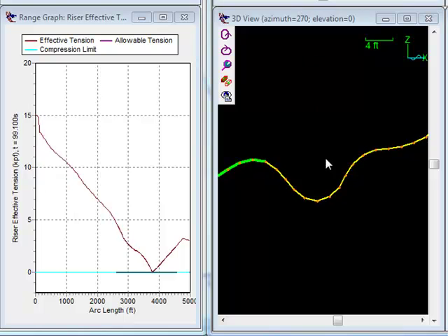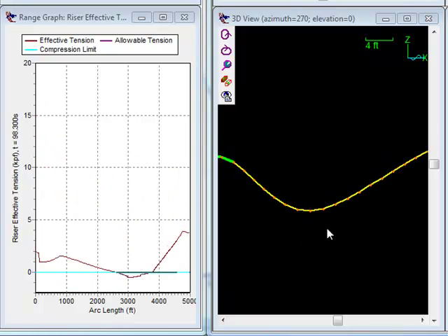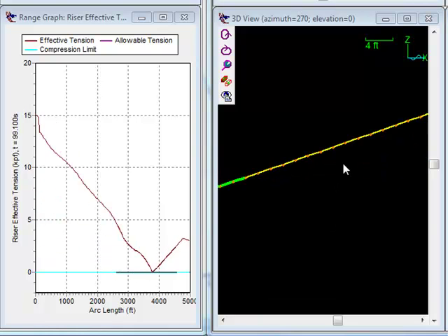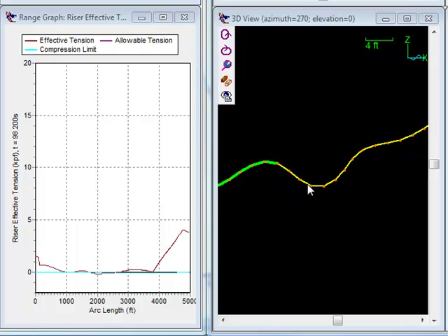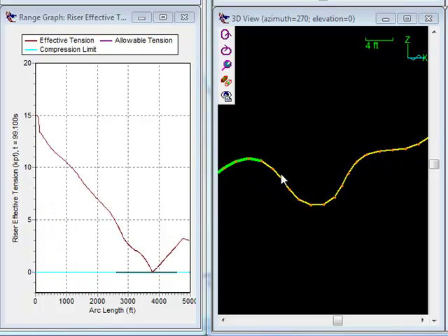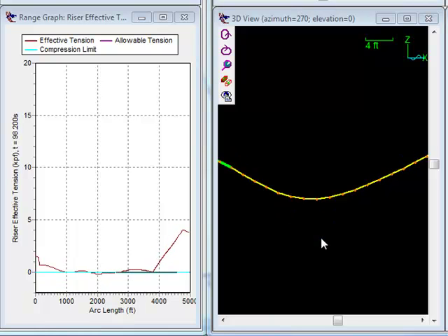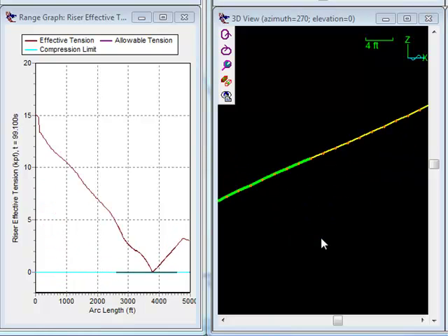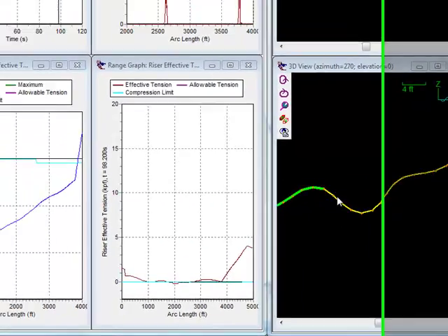Now, I've noted that the riser makeup here in the OrcaFlex model was with very fine segmentation. The element lengths are about 2 feet, and these are much shorter than in our normal runs in this project. These runs take much longer to execute.